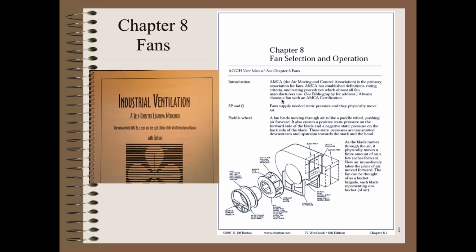And then you go up 30 feet with 12-inch ductwork. Maybe just another K times 30 feet times the velocity pressure, maybe it's half an inch. So maybe you need 2 inches of positive static pressure to make up for that loss, the energy losses, sucking the air here and pushing it out there so you don't lose the energy on this side. You're right? The same charts we use? Exactly the same charts. Okay. You work it exactly the same way, except now you're working with a positive pressure and it's building up over here.